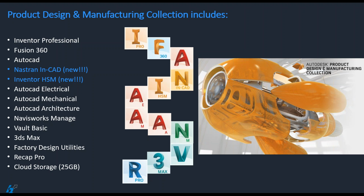Great. All right. You got one more question. Can Fusion 360 open Inventor files? I believe it says so. I know that Fusion uses an upload command. Yeah, so Inventor can open Fusion 360 files natively? The Fusion 360 file is like an F3D file, and Inventor does not have that option. So you will need to use a translator between the two. That's why I did in my demo earlier. I used a STEP file to make that translation, and hopefully they will have a way where Fusion 360 and Inventor can open each other's files natively, just like Inventor can open SolidWorks files.